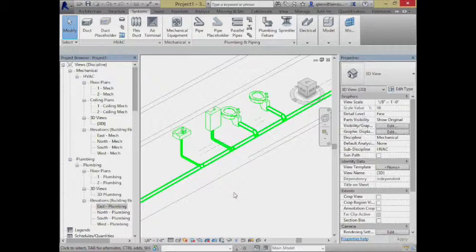Okay, so you go through and put the sanitary system in. That's looking pretty good. For the routing that's going on here, let's talk about that. Routing is really all about, from a specific type of fixture and whatever its output is, connect it through to the lateral line, the main line that you want to have carry the waste away in this case, and connect in the appropriate pipe segments and connections to make a more orderly and sensible transition between those things.